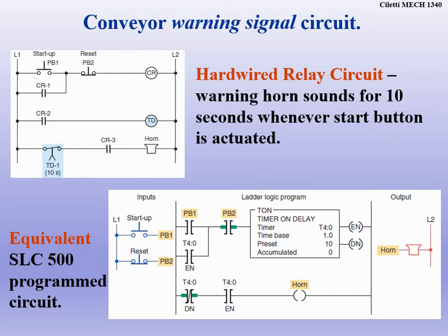When we do the enable, that's going to go around push button 1. Does everybody see that? So when we hit push button 1, we're using the enable and the do not enable down below, because we always have the outputs, the true and the false coming out of the timer there.